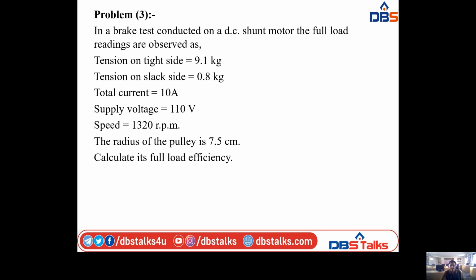And for the motor, we have to calculate the motor input. So that is motor input is equal to V into I. Here the voltage is 200 volts into current is 40 amperes, and finally we have the motor input 8000 watts, and armature copper loss is (RA plus RSC) into IA square. So here I am taking the motor and generator separately. That's why here I am taking armature resistance 0.4 plus the series field resistance 0.375, into armature current 40 amperes square, that is equal to 1240 watts.